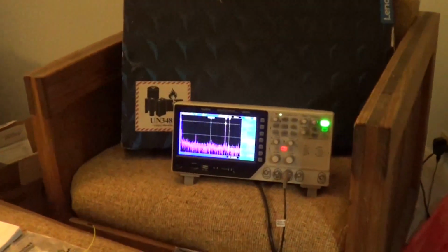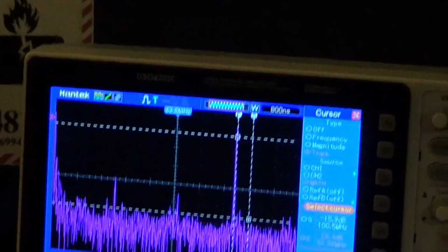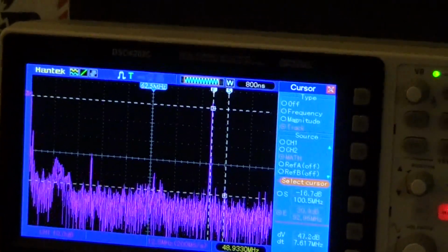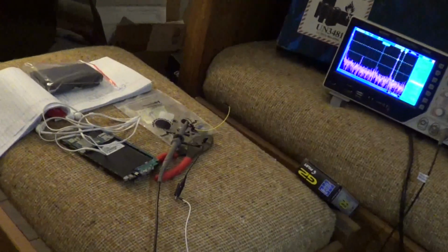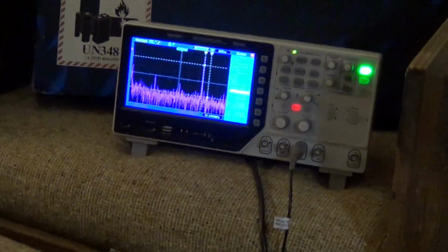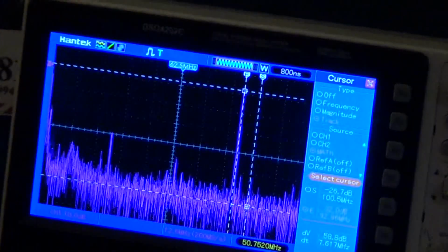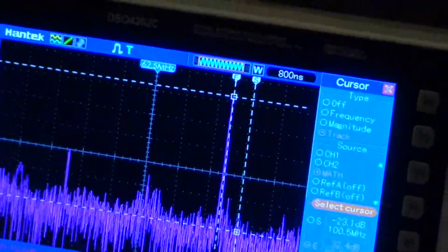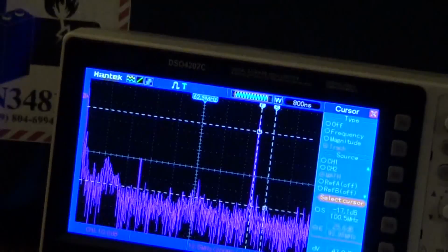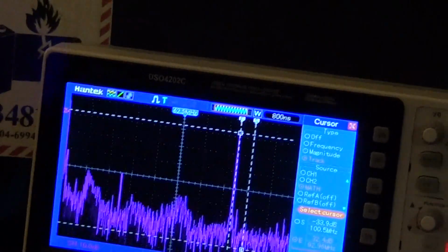The interesting thing is I have an actual oscilloscope, a 200 megahertz oscilloscope, and right now I have it set to math FFT, fast Fourier transform, on the yellow cable. They act like an antenna for detecting signals, and because we're transmitting and close enough to the source, we can detect it, and there is a peak. The peak in an FFT corresponds to the frequency of the oscillation, or the sine function,